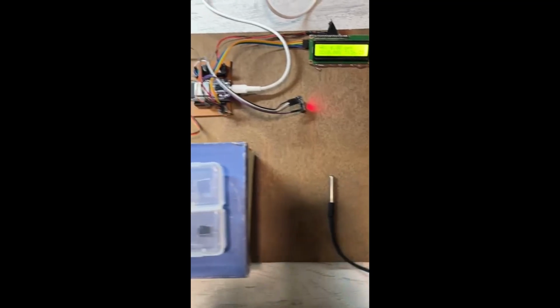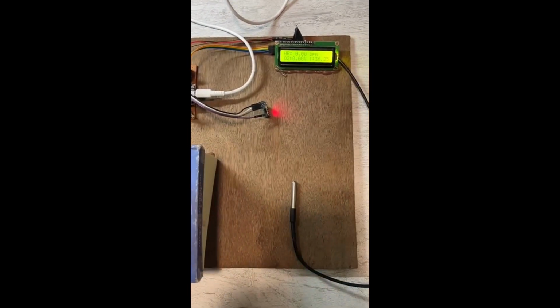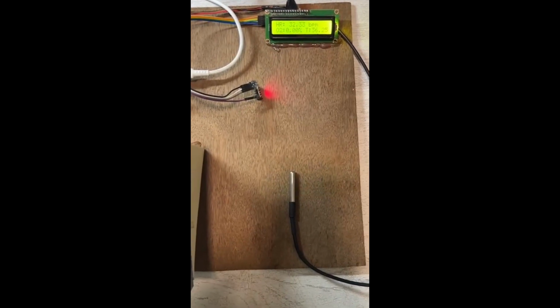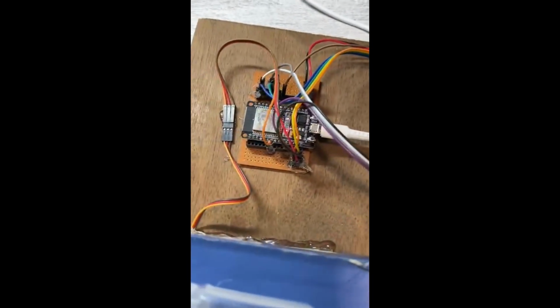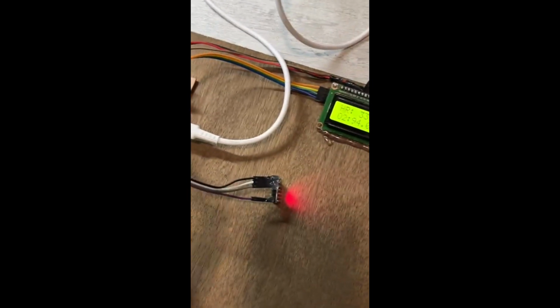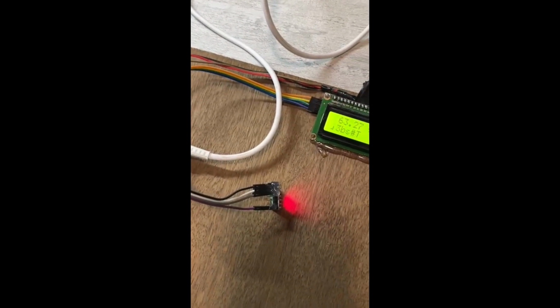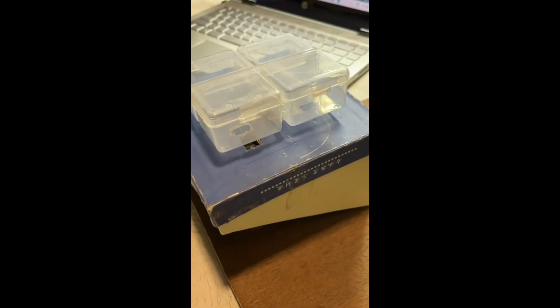This is our IoT model health monitoring system. We have used the DS18B20 temperature sensor. We have used a 16x2 LCD. We have used an ESP32 development board, and we have used this MAX30100 oximeter to calculate heart rate and oxygen level. And we have used an SG90 servo motor to drop the pills according to the time period. It drops the pills from here and the pills appear according to the time. We have set the time to 30 seconds for now, for morning, afternoon and dinner time.